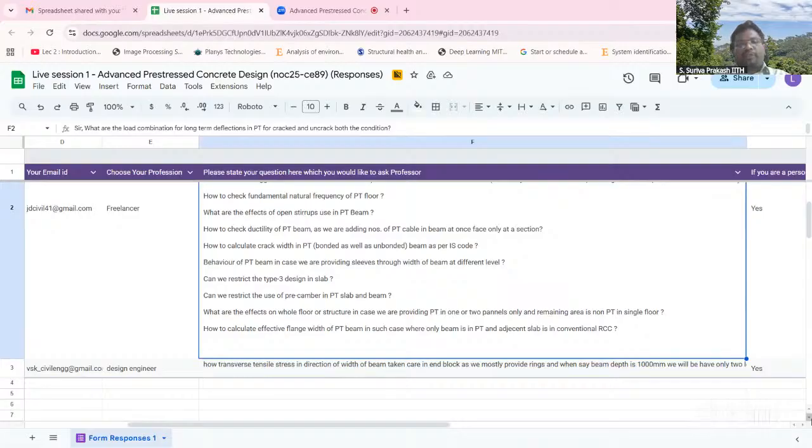There are ways you can idealize the load deflection as a bilinear curve, and you can measure the displacement or deformation ductility also. But that's a member level behavior, it's more involved. Or you can use commercially available freeware, like Response 2000, which is a very nice software that was developed at the University of Toronto, right? You can model the PT beam and find the load deformation behavior of the beam to find out the member level ductility. But typically in design offices, we check only the cross-section ductility to ensure that you have adequate curvature ductility, right?